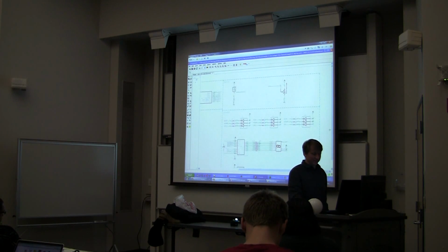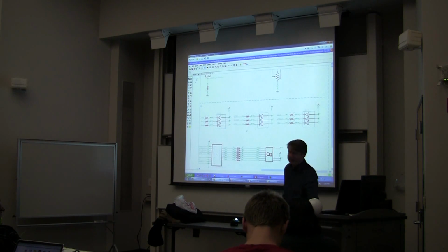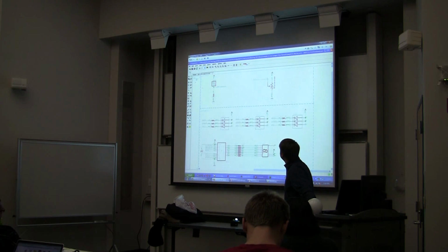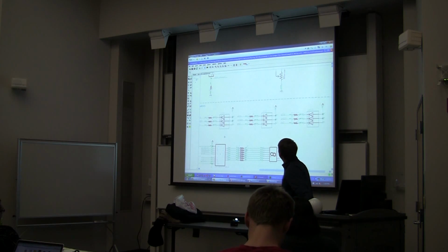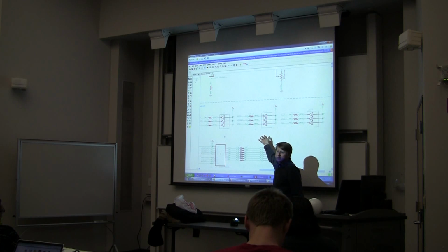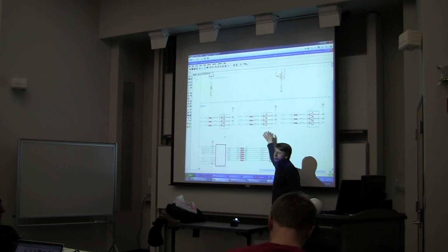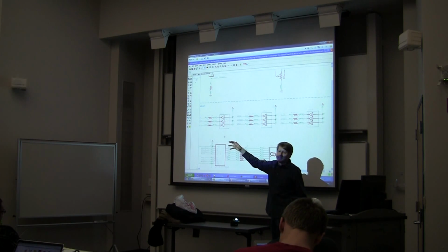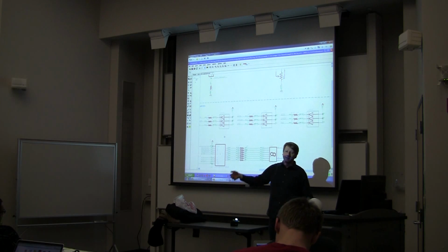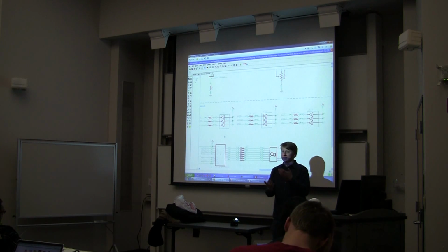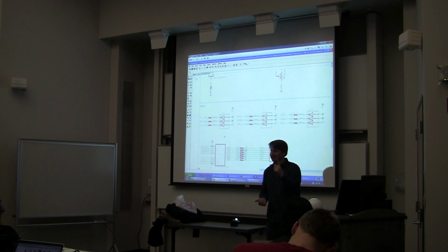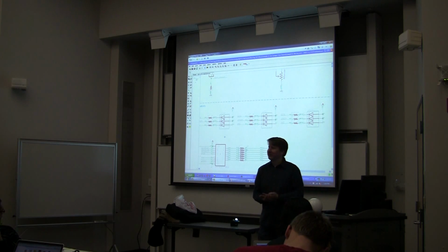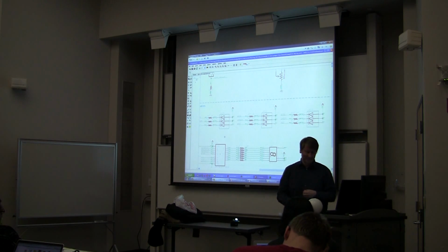And you're going to get feedback back. And one of the things that, for instance, on this design, you get some grumpy things saying, too many LEDs for 3 pins. Right, because this is not going to glow very bright. Your LEDs are meant to draw crazy amounts of current and blind you. We're driving one of those LEDs with the pins. You can't drive 3 of those LEDs with one set of pins.